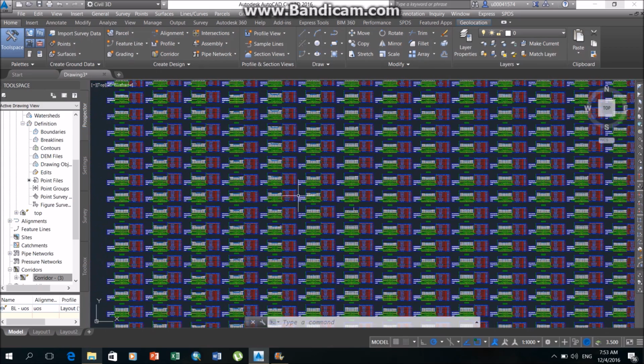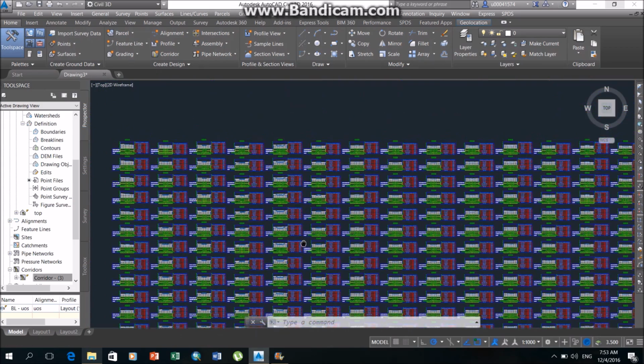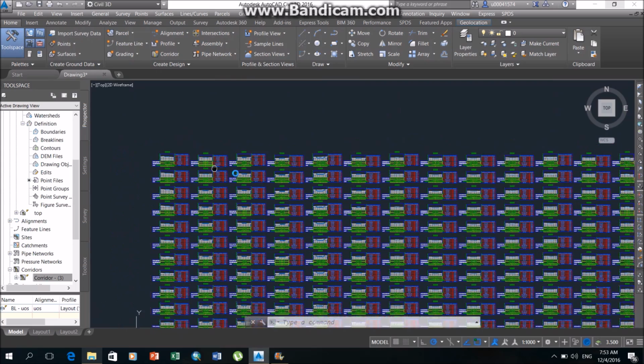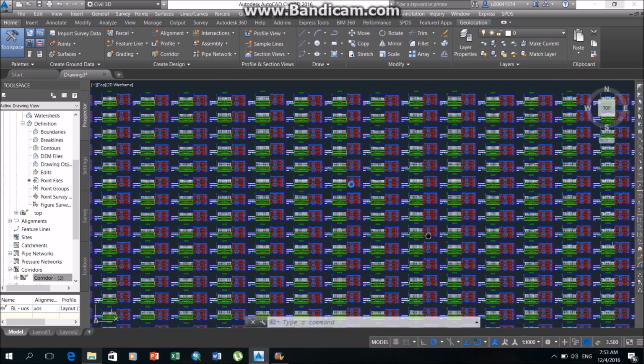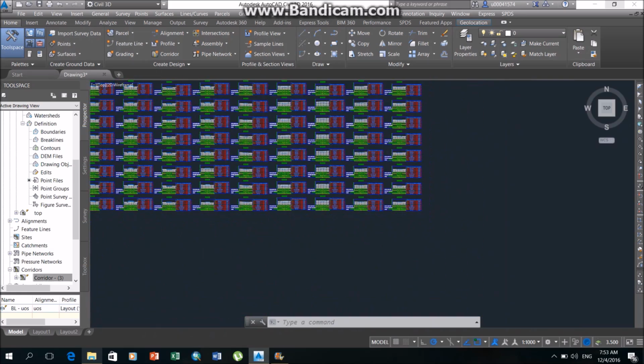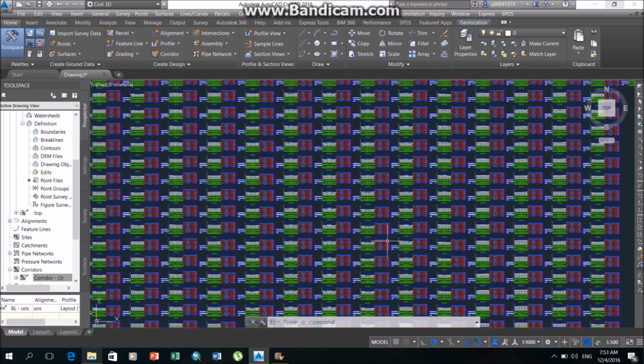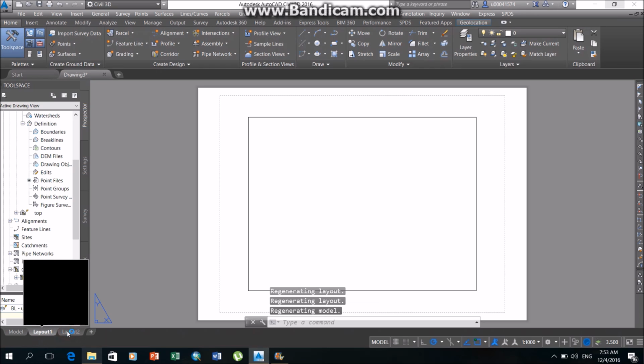You have all the stations with their cut and fill amounts on the schedule, and all cross sections and all stations from 0 to the point you have finished on. You can simply print them on PDF or use them from the layout. You can edit your page as a normal AutoCAD file.